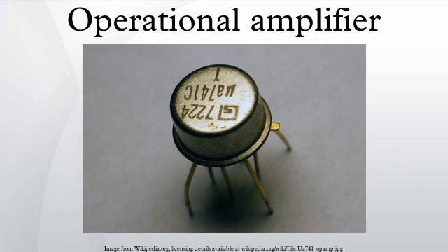None of these ideals can be perfectly realized. A real op-amp may be modeled with non-infinite or non-zero parameters using equivalent resistors and capacitors in the op-amp model. The designer can then include these effects into the overall performance of the final circuit. Some parameters may turn out to have negligible effect on the final design while others represent actual limitations of the final performance that must be evaluated. Real op-amps differ from the ideal model in various aspects.